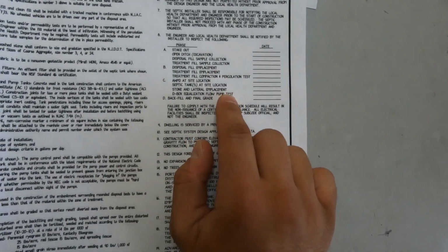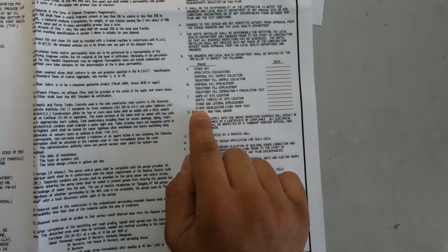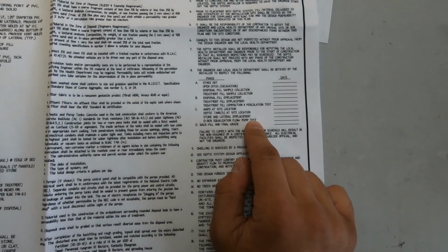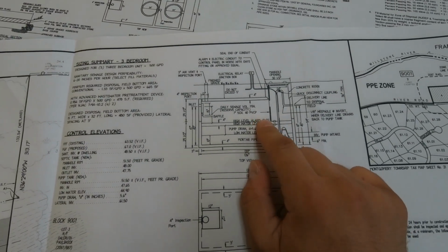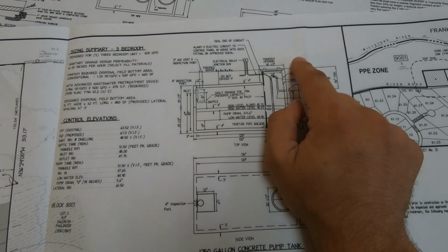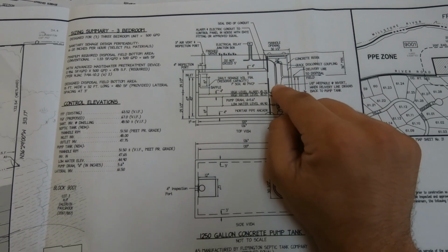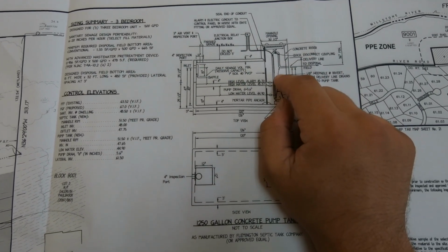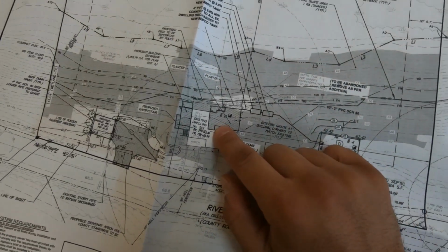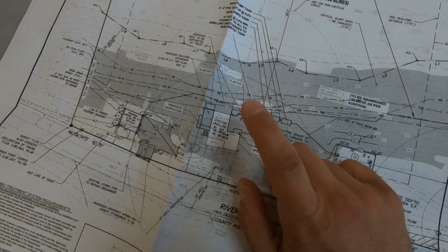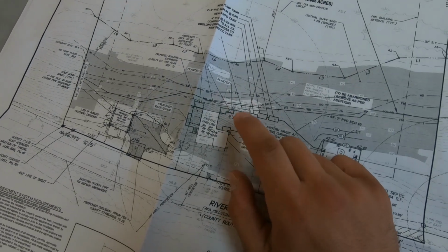And that's the last checkbox item here, right? D-box equalization / pump test. While that pump test is going on, you're also going to want to check the high level alarm. So usually what they'll do is they'll put a shovel in here, they'll lift up this float, and then you'll be able to hear the alarm. Sometimes you can hear it from the field. Sometimes you have to walk closer to the dwelling just to hear the alarm, but make sure you check that while they're doing the pump test.